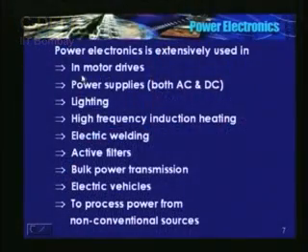Major application is in motor drives. Motor drives, to control the speed or to vary the speed over a wide range, because almost all machines, like separately excited DC machine, induction machine, constant speed motors, the application requires a wide variation in speed. You have to use a power electronic converter.